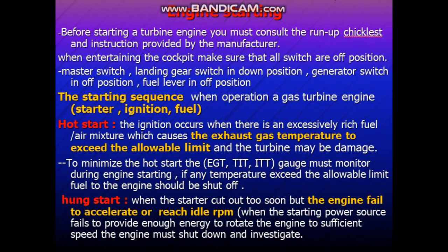Engine starting. Before starting a turbine engine, you must consult the run-up checklist and instructions provided by the manufacturer. As we talked before, you have to have a checklist and the instructions given to us by the manufacturer. When entering the cockpit, make sure that all switches are in the off position.